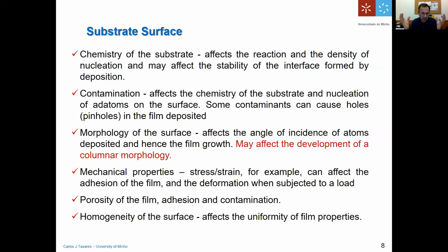It was one kind of arrangement of atoms on its structure, and you're trying to deposit the material that will crystallize in a certain form. And when these first atoms reach the substrate, they might find some difficulty in trying to accommodate themselves on the surface of the substrate. And so some intrinsic stresses are generated. For example, if the deposition is made at a high temperature, then the thermal lattice expansion of both the substrate and the thin film has to match, otherwise you will generate thermal stresses.